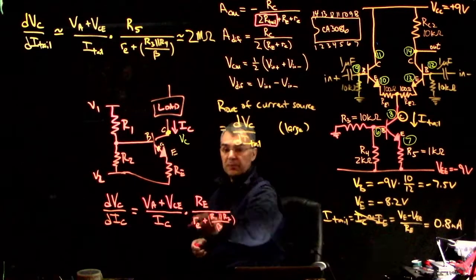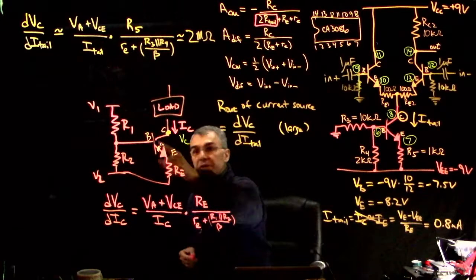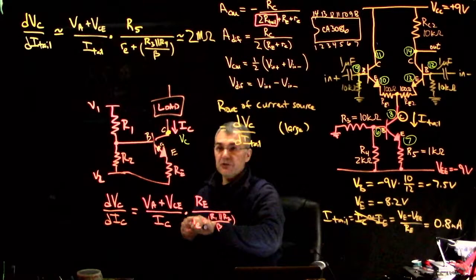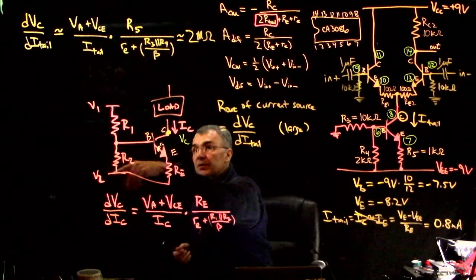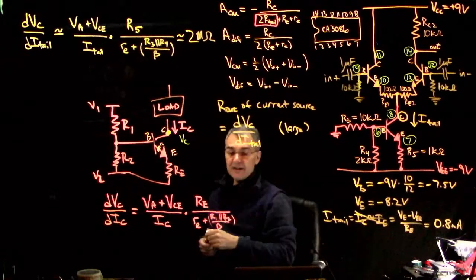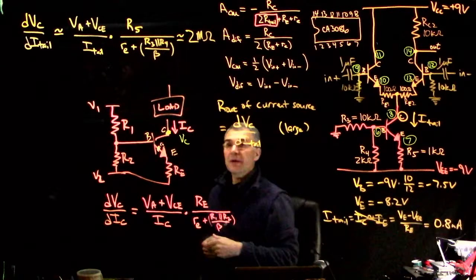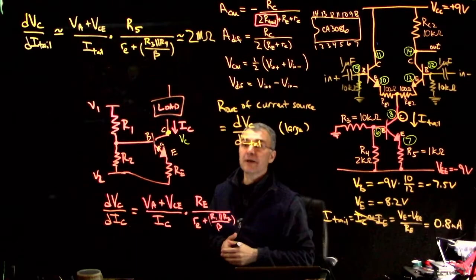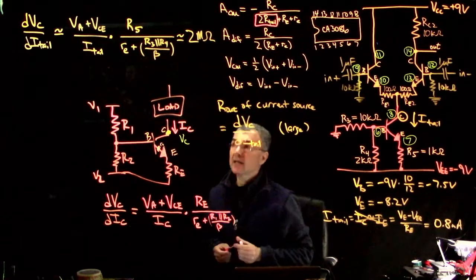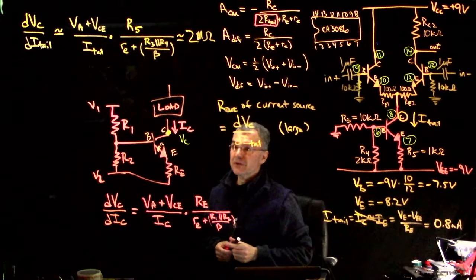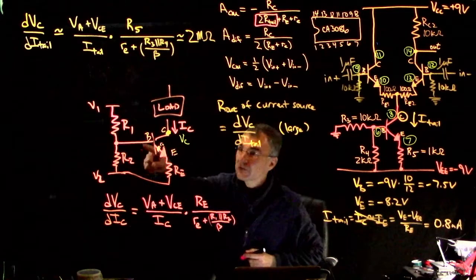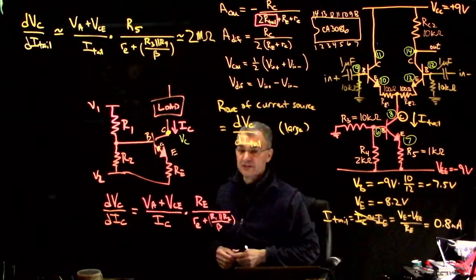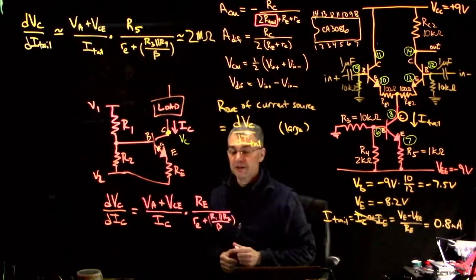So this is the resistance you see looking up into the emitter. You see this little RE, and then you also see what's behind the base, but divided by a factor of beta. I think in the original expression it was beta plus 1. I treated beta as big enough that beta and beta plus 1 are the same thing. And there are a couple other small things that I neglected, so I only put big things divided by beta.